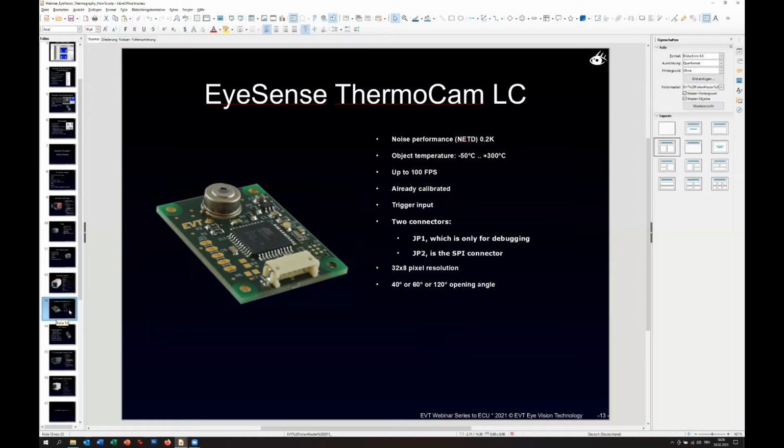The interesting thing is also what high-res means. The interesting thing is what you have to have in your mind for thermal imaging cameras. High-res starts at 640 by 480. This is very high-res. So the average cameras are between 160 by 120, up to 640 by 480. That means 640 by 480, the very old standard for gray cameras from, let's say, 25 years ago, is the high-res standard for thermal imaging.